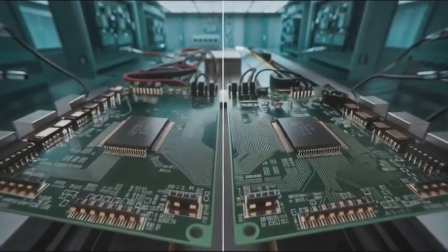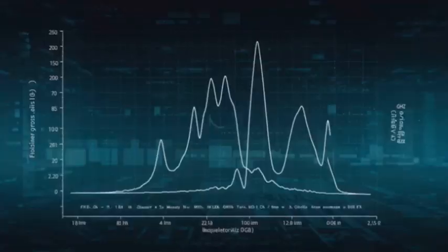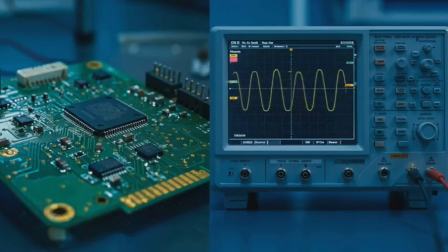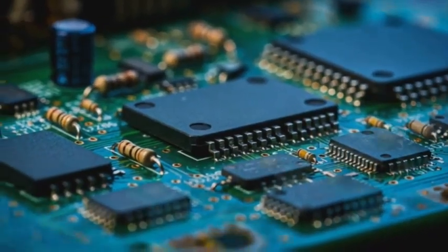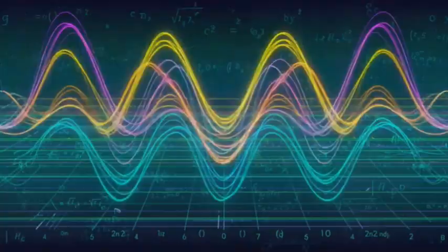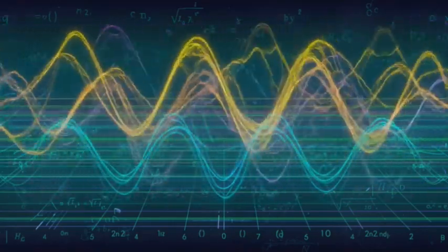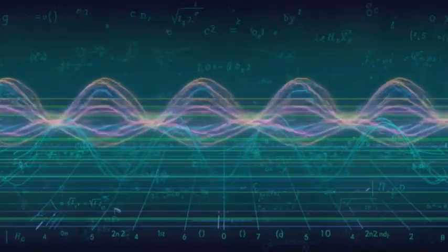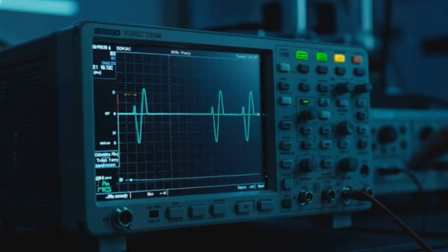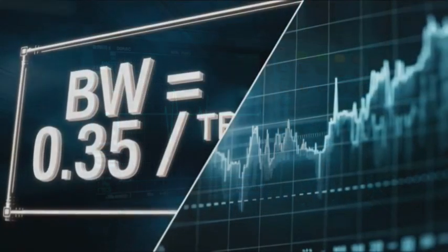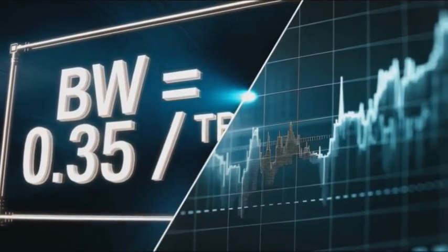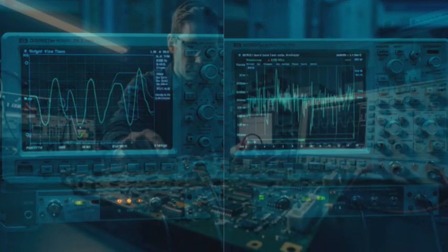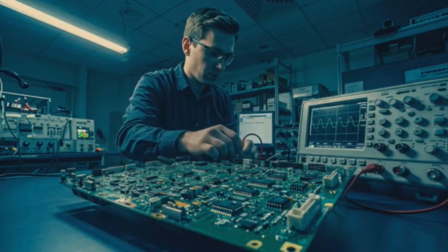Digital signals like a 10 megahertz square wave actually contain frequency components extending to gigahertz. The Fourier theorem explains this through sinusoidal harmonics, decreasing rapidly at higher frequencies. The bandwidth limit, determined by rise time, marks where these harmonics become negligible. For instance, a 1 nanosecond rise time has a bandwidth limit at 318 megahertz.